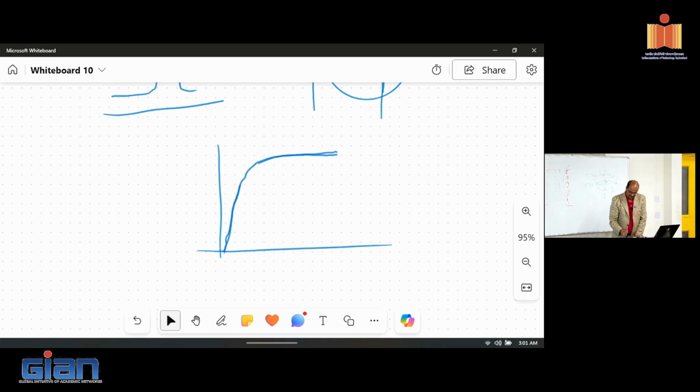It performed like this. Now, if I do a precast and put the same displacement, so I'm basically trying to match each and every displacement, I will go something like this. And it may actually fail sooner because you're overstraining it. But when people do the test, what they report, I've seen it in published papers, they will say precast is behaving better and give you better resistance.